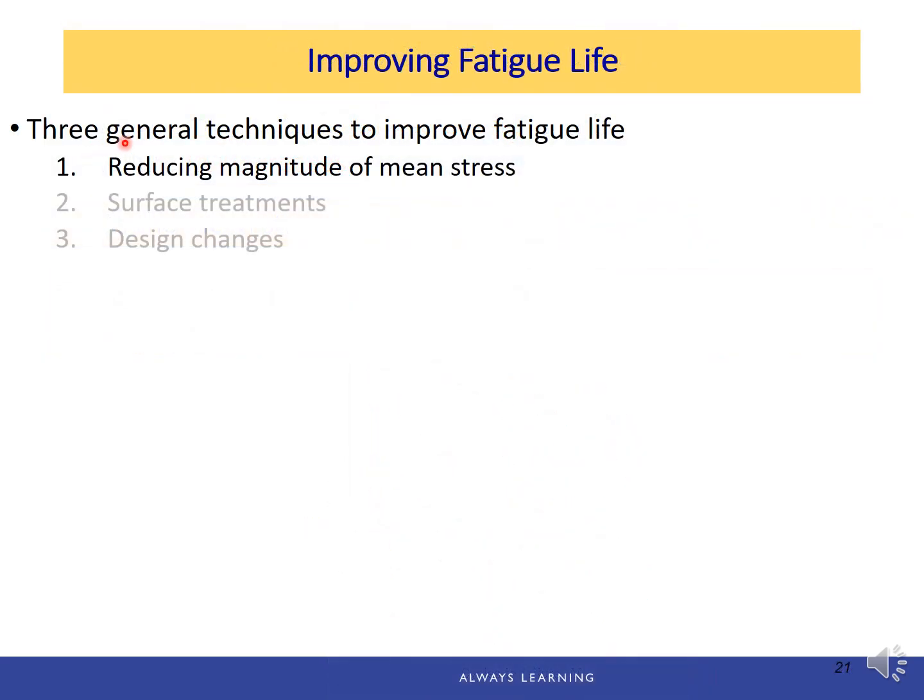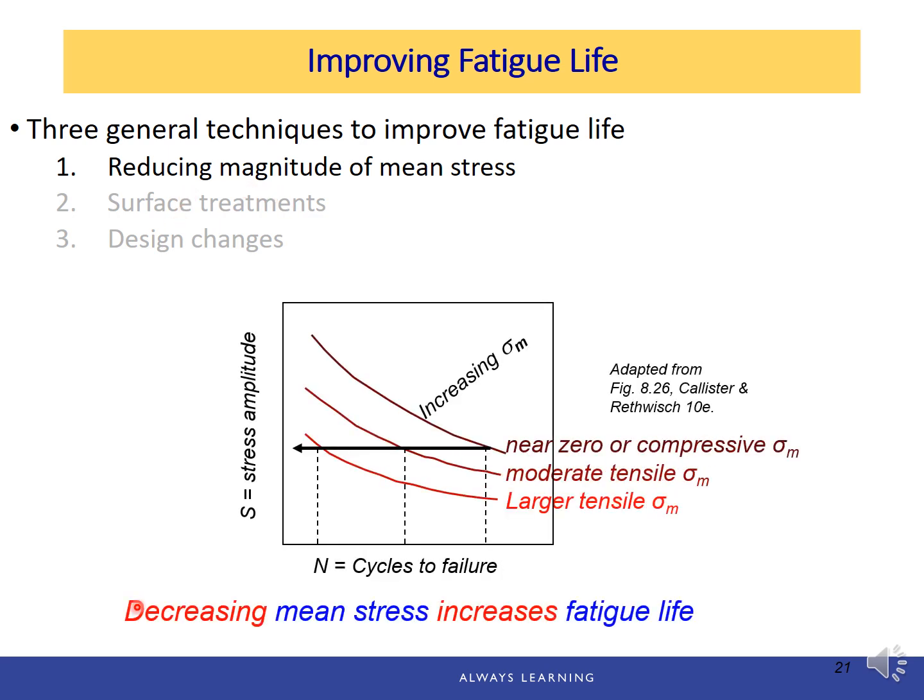There are 3 general techniques to improve the fatigue life. First is to reduce the magnitude of mean stress. The second is surface treatment. And third is design changes. And we just mentioned the first one, which is that decreasing the mean stress will increase the fatigue life.